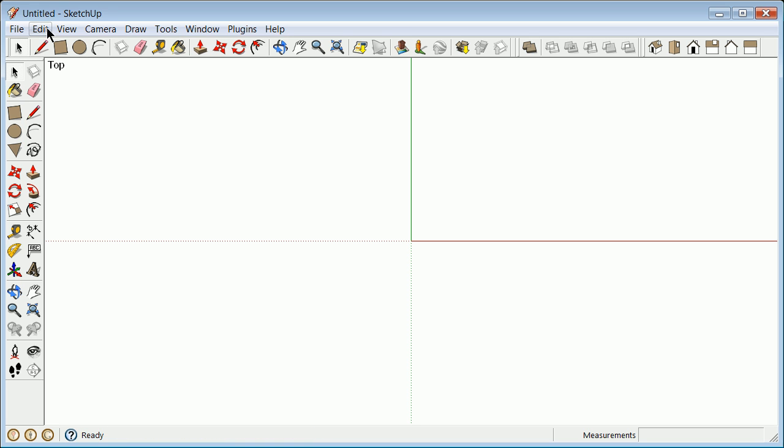All right. Now to the drafting. SketchUp does not act like AutoCAD, and if you try to make it act like AutoCAD, you're going to be whacked. However, you're going to try to use some of the basic skills that you've learned in terms of offsetting to draft in SketchUp like you would in AutoCAD, because a lot of engineering work is done by offsets and then tangent, tangent, radius.